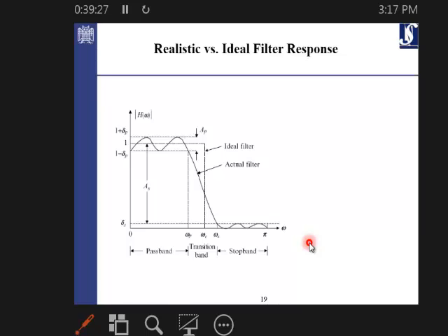The point is that in many cases, you have some oscillations in the stop band and the pass band, and you will have different filters based on the degree of the filter; this steepness will differ. You can have something very sharp or something going very smoothly from the pass band to the stop band, depending on the degree of the filter.